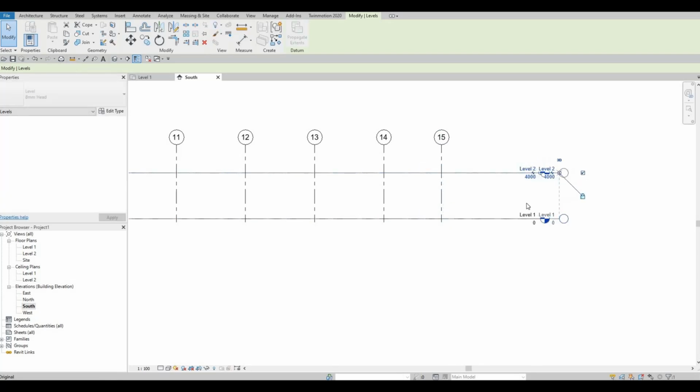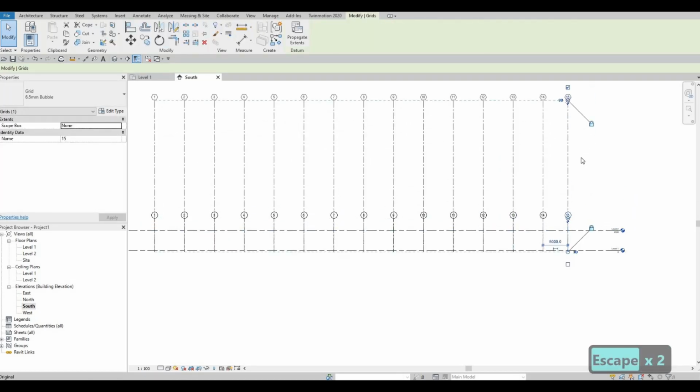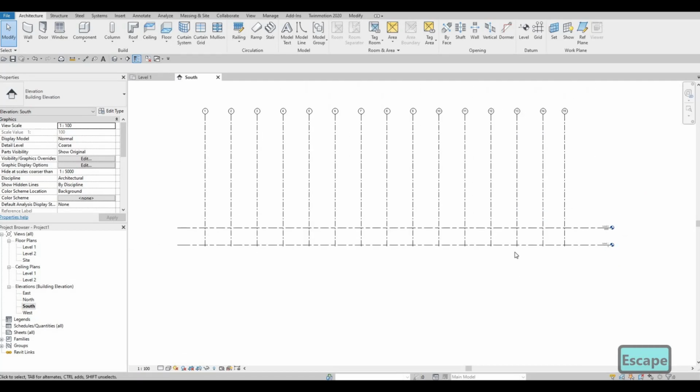And then this is going to be multiple stories. So what I usually do is I'm just gonna move it like that for now because we have different floor plans, which is the first, second, and third, and then we have the typical floor that we will be copying multiple times and then grouping them all together and pasting it to our clipboard to copy to all remaining floors.